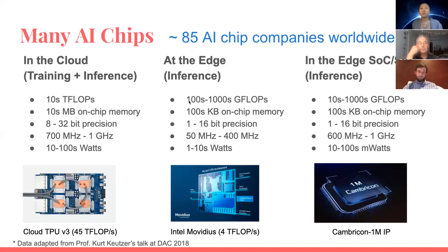So in this case, these will have way less compute capacity with less on-chip memory, and then they sometimes will only compute lower precision workloads. They don't have any capability of performing high precision computation. They are composed of only low precision computation units in order to keep them very small and efficient, and they run at lower frequency so that they consume less power.